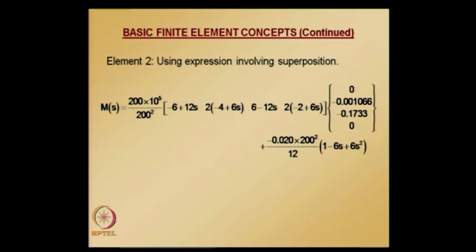Element 2. The first part is interpolation using finite element shape functions, and the second part comes from fixed end moment correction. Here this fixed end moment expression corresponds to a fixed end beam subjected to distributed load.